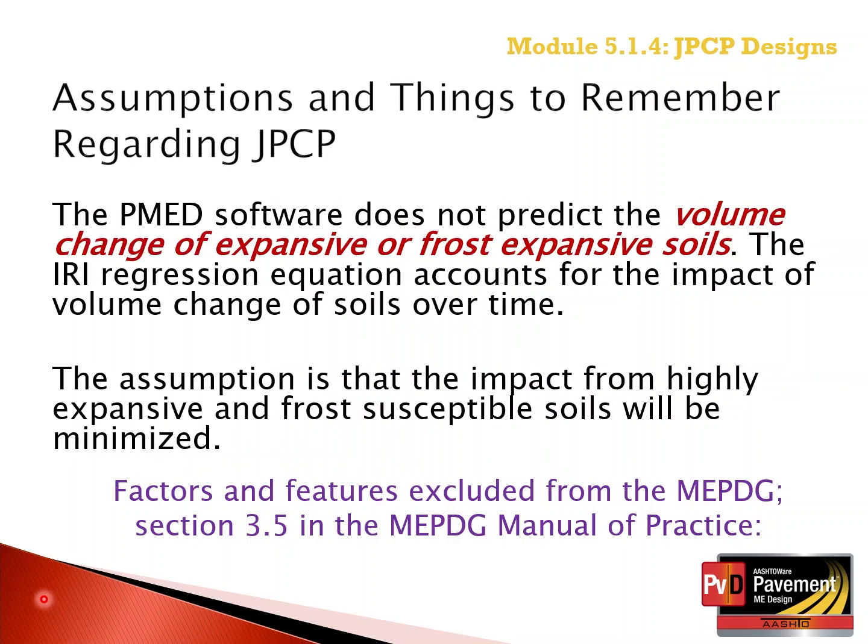As mentioned in the MEPDG Manual of Practice under Chapter 3.5, Factors and Features Excluded from the MEPDG, volume change of the soils in terms of frost heave and or frost susceptible soils and or potential vertical rise from expansive soils is not predicted by the software.